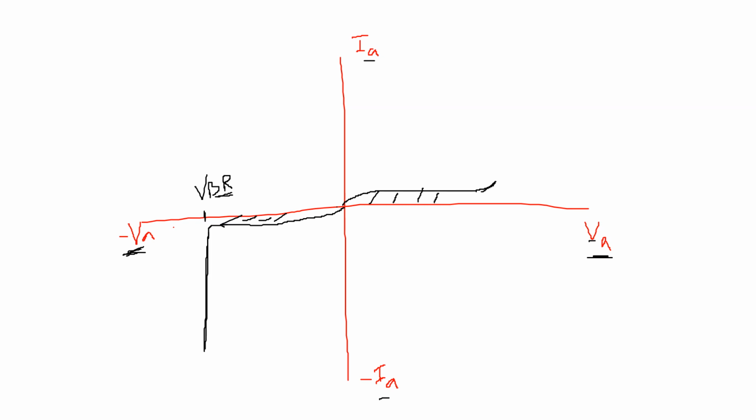By increasing this forward voltage, at a particular voltage, that is the forward breakover voltage, the SCR starts conducting, meaning the SCR acts as a short circuit. Under the short circuit condition the voltage decreases and the current increases.